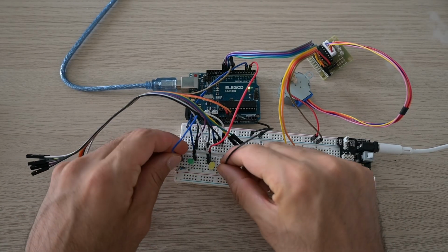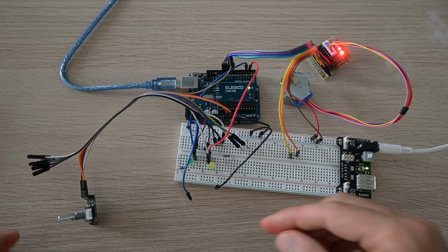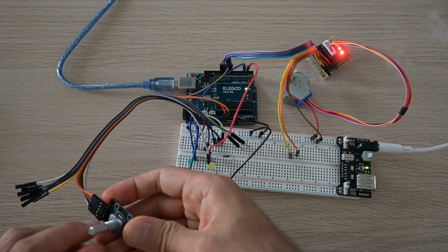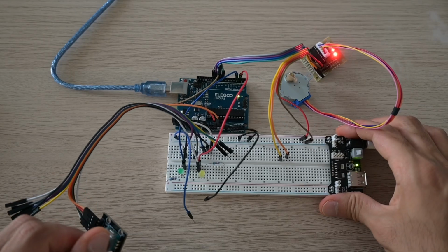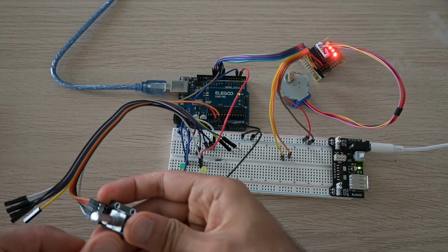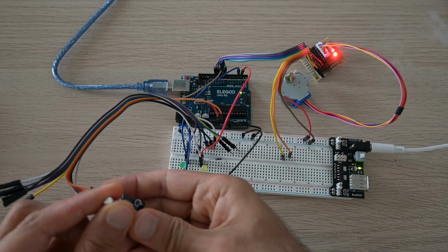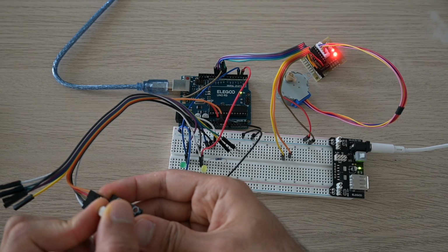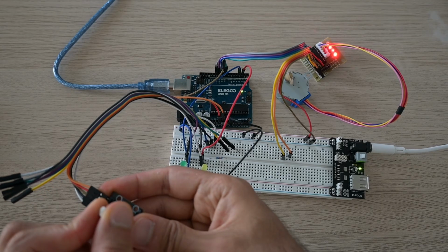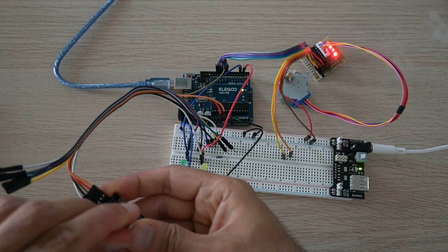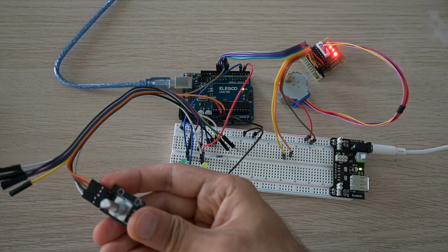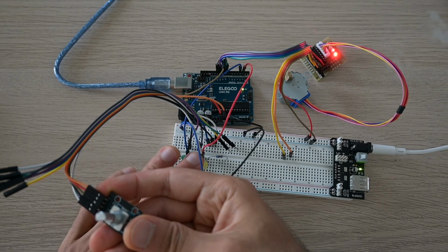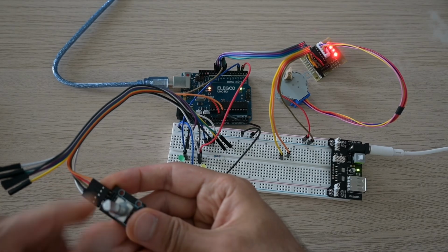We'll now finish this demonstration, and the LEDs are disconnected so that the main circuit is driven instead. Now we'll have the signals coming through our Arduino inputs, and we can interpret these signals leveraging the concepts that we've seen before. Plus, we also make sure to trigger the device interrupts not only for one of the inputs, as was done in the previous script, but for both inputs, so that we can capture all movements correctly. As a result, the motor now precisely captures all the inputs we provide through the rotary encoder.